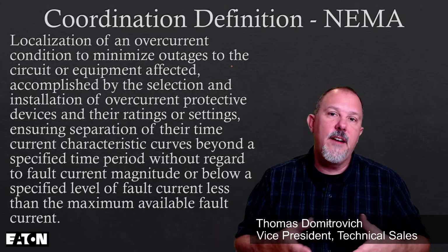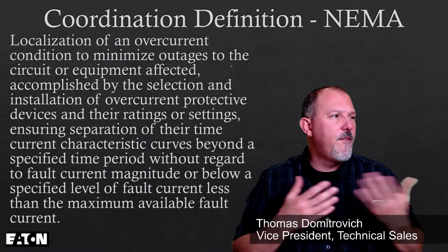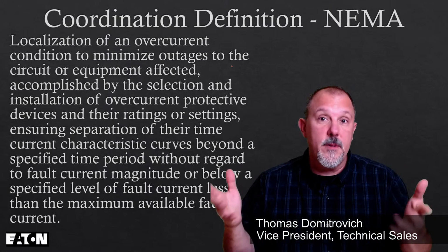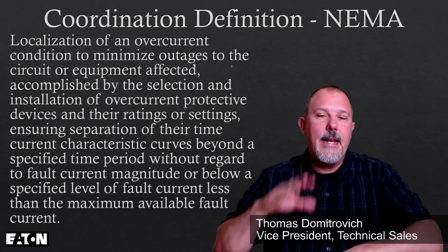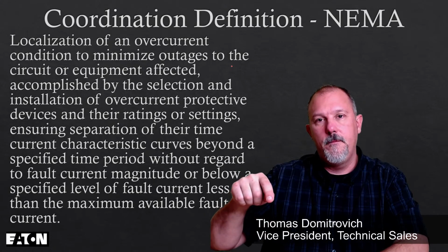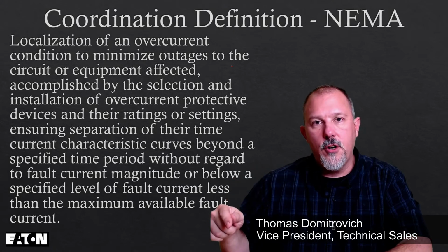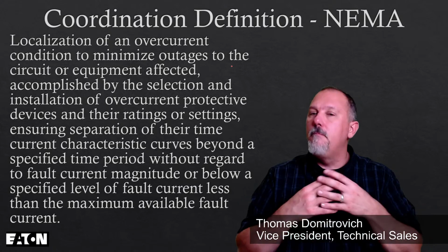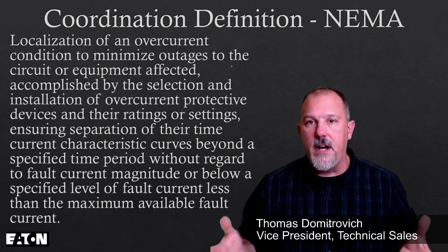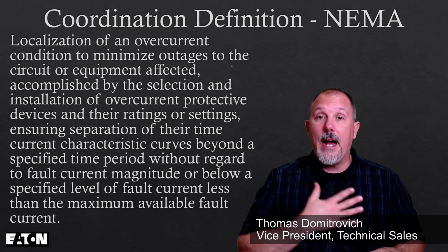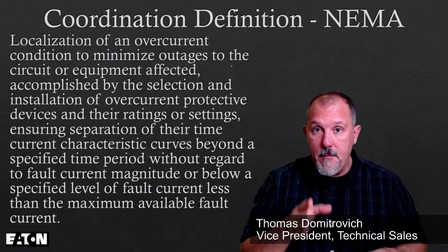And then I would leverage the Red Book. Well, I think it's IEEE 141 or 242. I can't remember the number, but it's the IEEE Red Book. In that book, they noted percentage values of the three-phase bolted fault current for arcing ground fault currents, which they would say are the most common fault that you will find in a power distribution system. And then I would do that math.